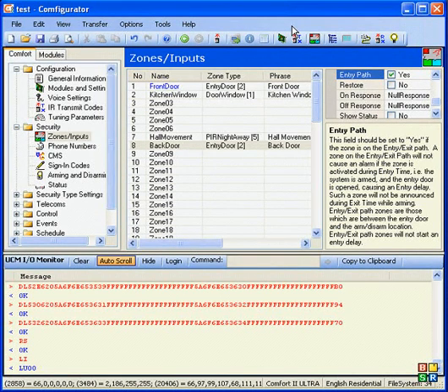Let's say security off. To test our zone programming, what we call the security check, we do this by going to the keypad and pressing F3. Press 1 for battery, 2 for security check. So in security check mode, any zones which are triggered, that means opened, will be announced on the keypad according to the zone words that you have programmed.